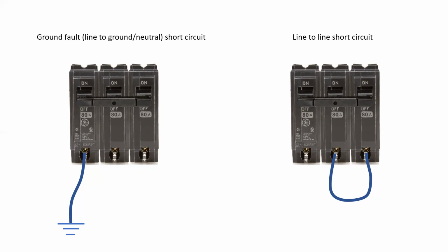The other is a ground fault, and usually we're working with a Y system that's solidly grounded, which means one of the ungrounded conductors coming into contact with metal or earth or the neutral will cause a short circuit, but it's known as a ground fault.